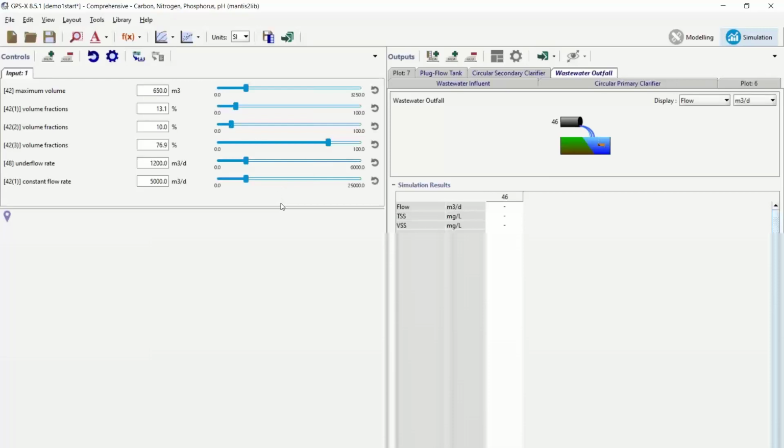We could even make the plant bigger. And so let's make this 800 in total, keeping all the proportions the same. And what does that do for us? 0.4. It didn't really make much difference. So this is an indication then of one of these aspects of this BNR system, playing around, making the plant bigger. That wasn't the problem, right? We were a little bit choked off on the recycle, maybe, for example.